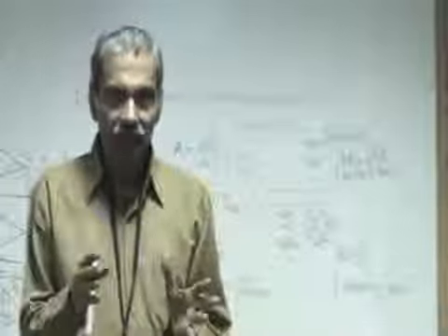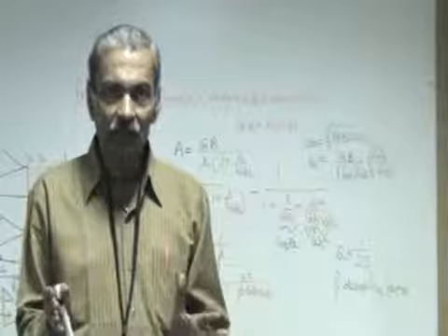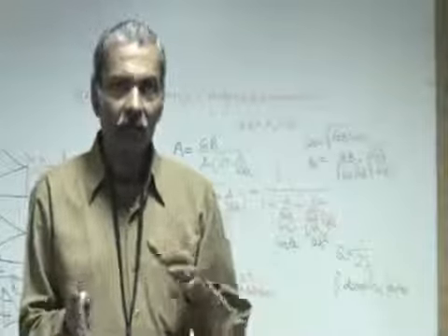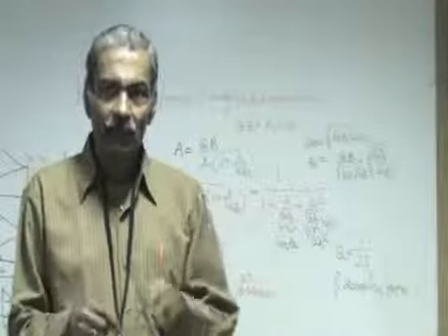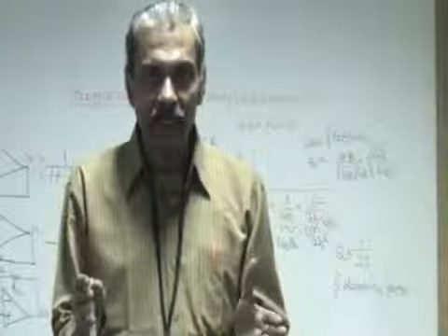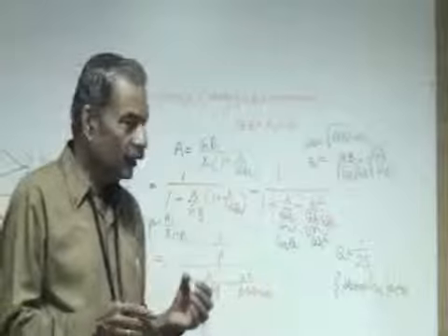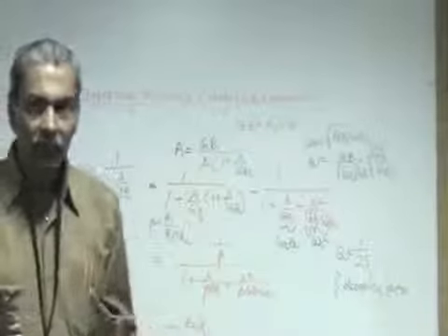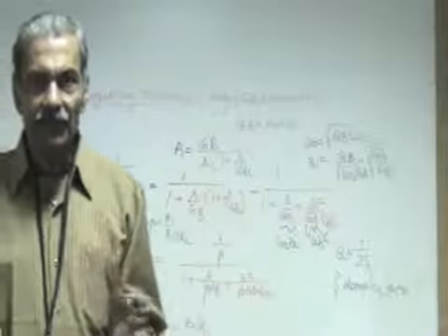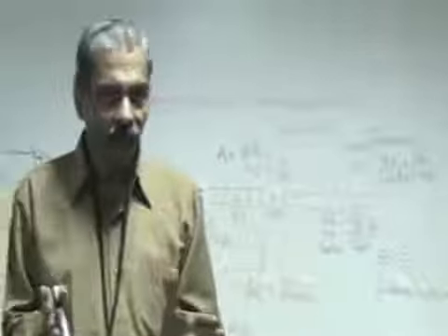And if the system is a first order system, then it will go on with an exponential rate, and that again takes an infinite amount of time for the system to come to steady state. We want an optimum result. So Q is normally made equal to 1, so that in the ringing there is just one peak, so that it quickly goes to steady state and settles there. And therefore this is a design measure. So we try to locate the second pole in such a manner that the transient response of the system becomes good. This therefore will facilitate a measurement of omega D2 and the gain bandwidth product of the op-amp.